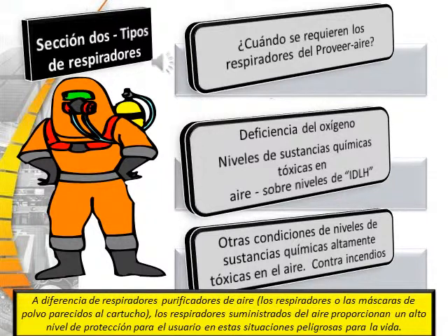When are supplied air respirators required? Oxygen deficiency situations, high levels of toxic chemicals above the IDLH, or immediately dangerous to life and health, other conditions of high levels of toxic chemicals in the air, as well as firefighting situations.